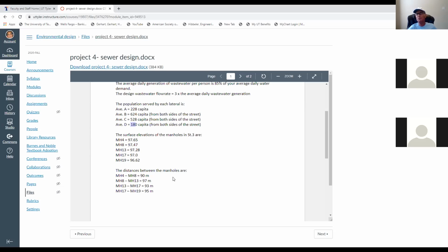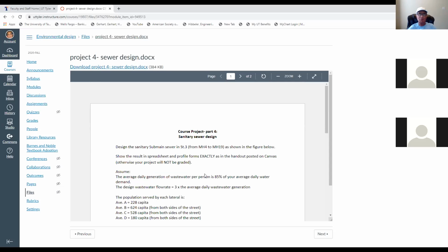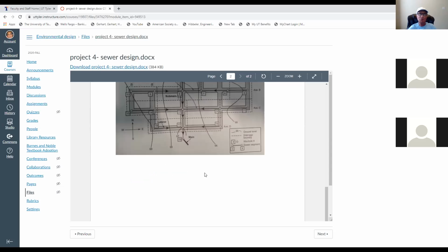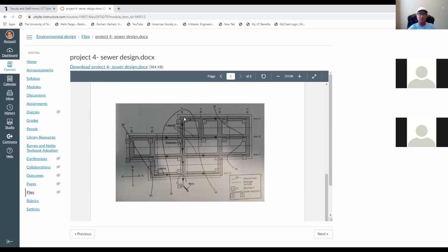Try the same things, you know. Slope of the sewer equals the slope of the surface. If it gives you a cleansing velocity that is at least 0.6 meters per second, flowing partially full, you are on the safe side. Otherwise, increase the slope. Okay, and keep going. It's very easy, just one sewer. I didn't make it more. Usually, I give the design plus this.